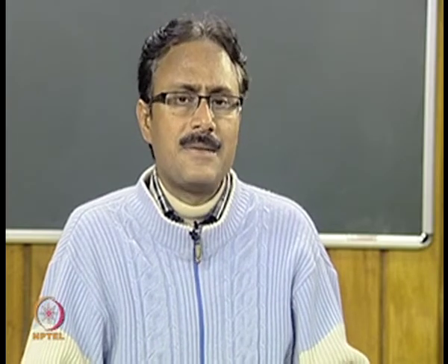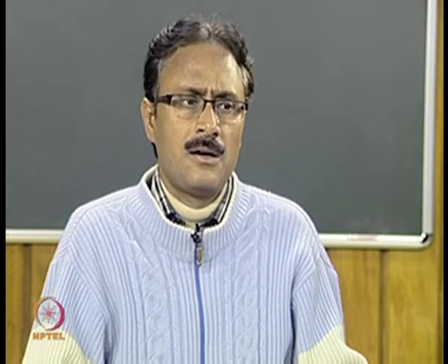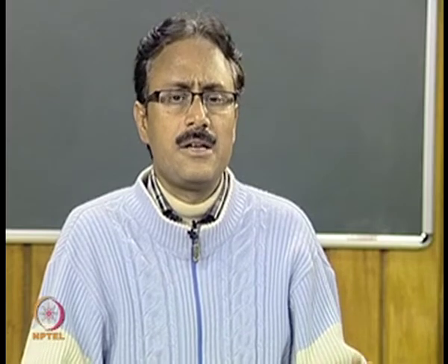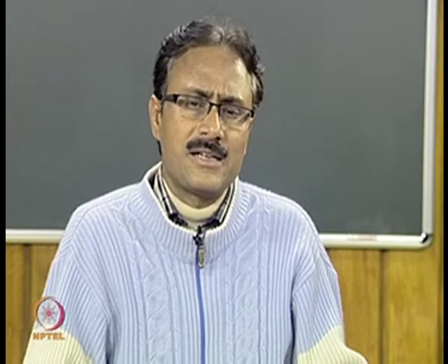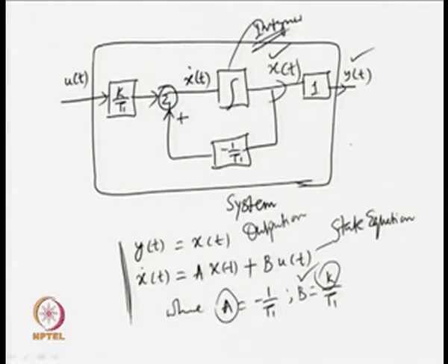When the system dynamics changes over time, it is necessary to identify the model parameters of a system, or whenever retuning of controllers is necessary, at that time identification of systems is also necessary. So, the identification can be effected at any instant of time. Because of that reason, initial conditions of the system when the relay test is performed are to be taken care of.